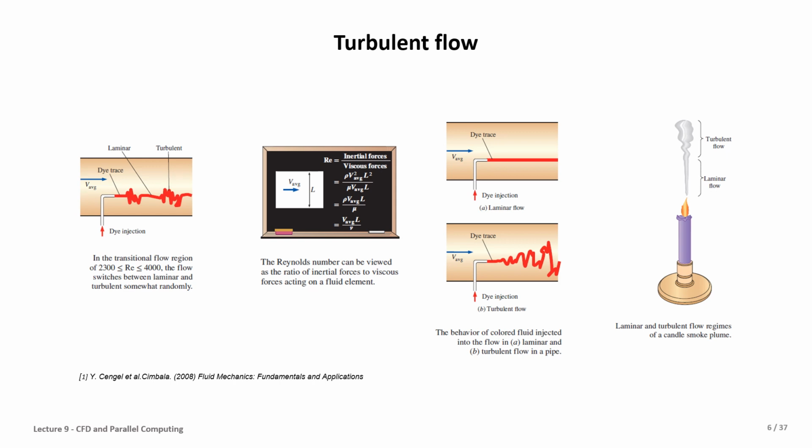However, in the beginning, it was imagination that maybe this hypothesis could cover all fields of the turbulent flow, but shortly it became clear that the Kolmogorov hypothesis, which is called K41 in the literature, has a limitation. The hypothesis has some assumptions regarding the homogeneity and isotropy of the eddies, which is only available on the small scale, not on the large scale.